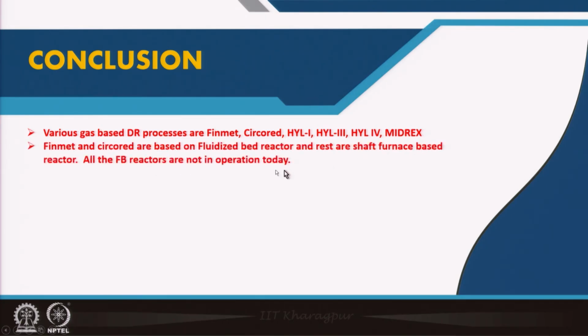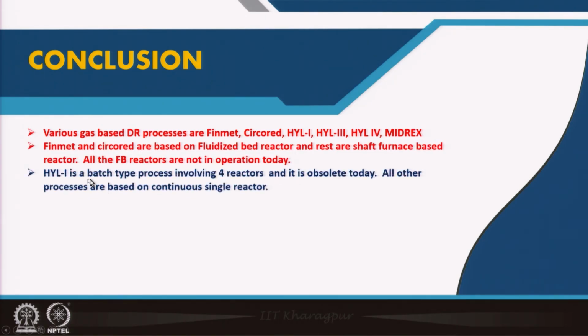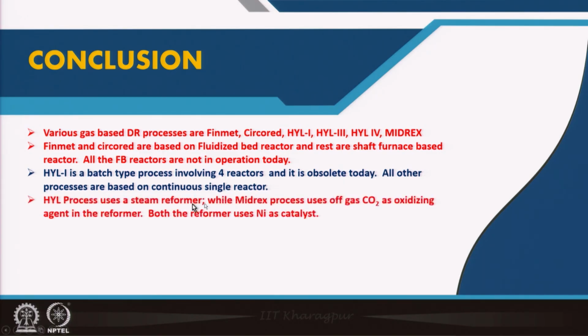So all the FB reactors are not in operation. And then HYL is a batch type reactor involving 4 reactors. It is also obsolete today because, as I said, it is energy intensive and productivity is less. The HYL process has a steam reformer, while midrex uses off gas CO2 as an oxidizing agent in the reformer.